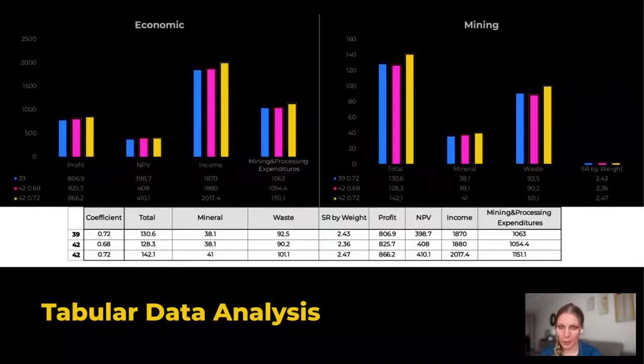The option with the steeper slope angle removes 12 million tons more rock mass than the option with the angle of 39 degrees. The ore is also 3 million tons more, and the overburden is 9 million tons more. The stripping ratio for the increment in ore overburden is 3 tons per ton, which is not very attractive, especially given that the total stripping ratio for the deposit is up to 2.55 tons per ton. So we need to pay attention to the adjustment factors with a lower value, and we'll compare it as a second option. So now let's focus on the economic indicators.